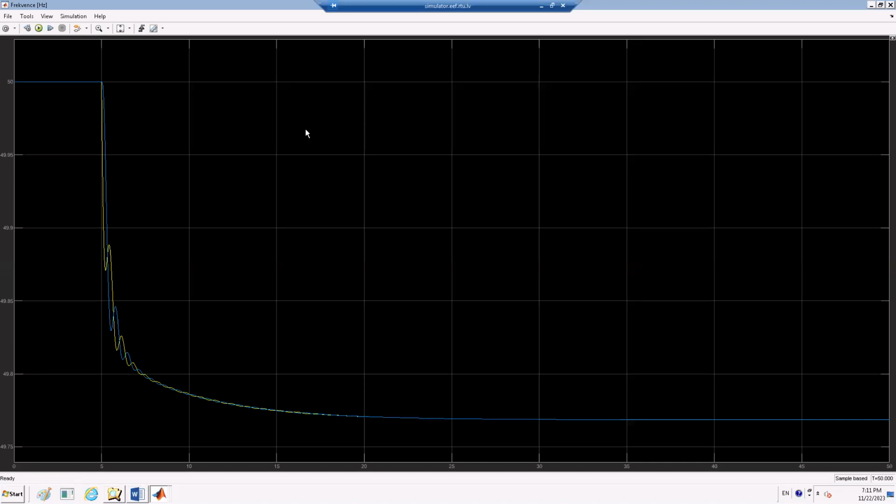The same as it was, for example, in the Italy blackout, as we discussed, due to all these issues that happened to the Italian power system, different generators stopped at different time moments with different issues. That's because the difference in voltage and the difference in frequency was not the same for all the generators. And here is an example of what is going on in the power network.